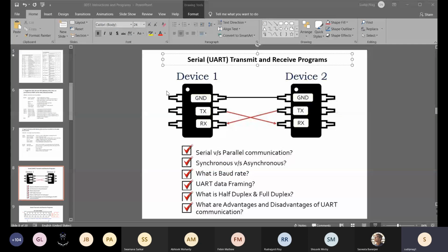The least significant bit comes immediately after the start, and the most significant bit comes at the very last, just before the stop signal. Now look at this for D0, D1. It's like rectangular boxes arranged in this timing waveform, whereas for the start, only the upper side of the box is missing.